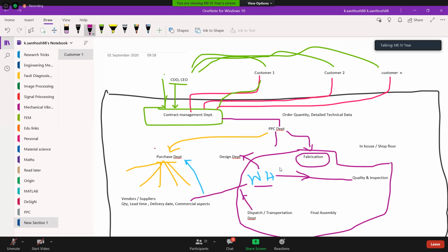in that case, they will go for simulation again with whatever material dimensions we received, 9.98 or something. So again they will go there, change the dimension, and run the simulation. If that is coming within the factor of safety levels, they will give acceptance to whatever material we received in the warehouse with the tolerance. After that, it will be stored in the warehouse. Somebody shouting.